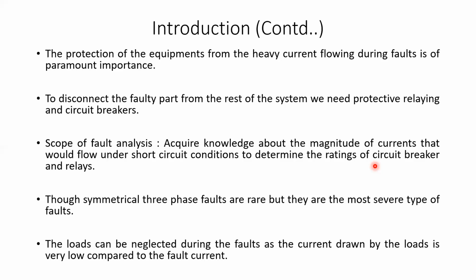Now, when we are going to implement this protective relaying and circuit breaker system, we need to know what is the maximum amount of current that may occur in the system in case of a fault. This knowledge will help us to decide the ratings of the relays and circuit breakers that we have to use for protection. So that is the scope of fault analysis: to acquire knowledge about the magnitude of currents that would flow under short circuit conditions, to determine the rating of the circuit breakers and relays.